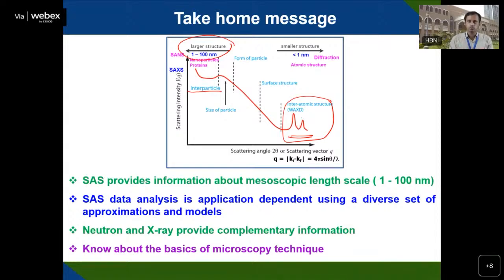So 0.002 to 1 nanometer, in that range you can vary. For example, for a 200 keV transmission electron microscope, the lambda is equal to 0.0025 nanometer. So you can see such a low wavelength you are able to get in the case of electrons. That's why you can see even smaller sizes of particles.